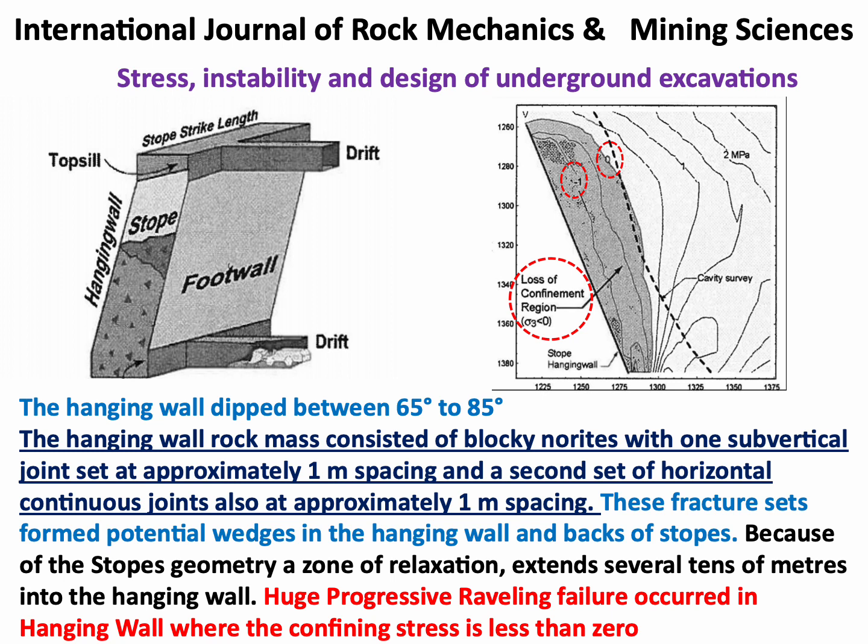The geological strength index of the rock ranged from 60 to 85 with compressive strength of 25 to 100 MPa and tensile strength of minus 0.4 to minus 2.65 MPa and a modulus of 27 to 80 GPa. The simple wedges thus formed in such a rock do not usually lead to progressive raveling.